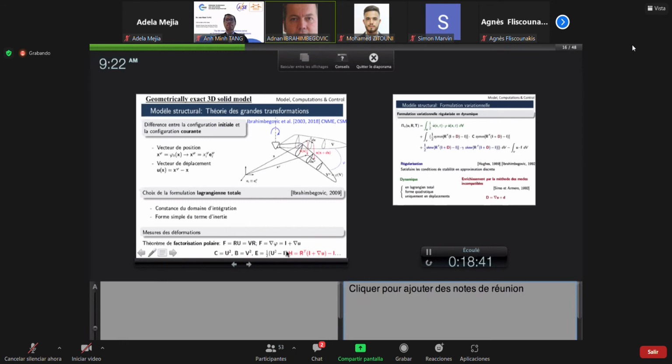In particular, we choose the so-called Biot strain, which is not the usual choice of Green-Lagrange and the like. It follows from the polar decomposition, where you split the deformation gradient into the rotation, which is the same rotation as the one you use for beams, and the stretch. Stretch is a strain measure which is kind of intrinsic. It's simply how much you stretch from the initial to the deformed configuration. If it becomes 2 times as big, you say the stretch is equal to 2. And then subtracting the identity tensor, you get the Biot strain.